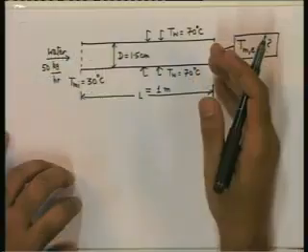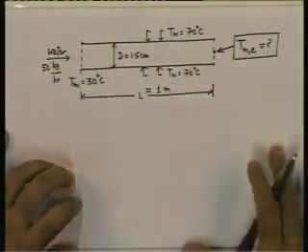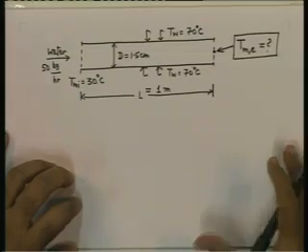Let us assume, just as a guess, that the exit temperature be 50. We are not estimating directly the exit temperature, but suppose it were 50, then the bulk mean temperature for property evaluation would be 40 degrees C. We already have listed with us properties at 40 degrees C, so that is a good assumption to start.